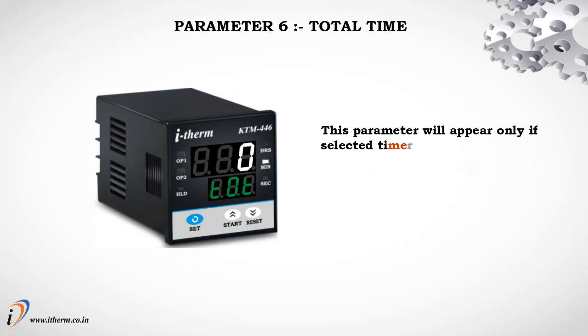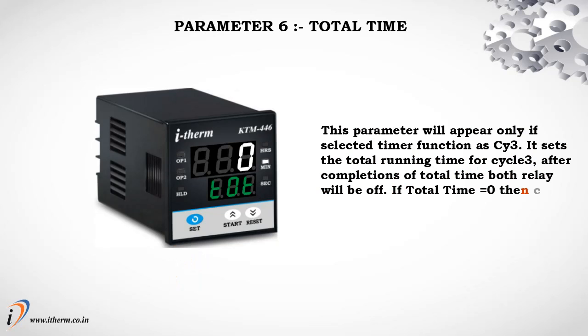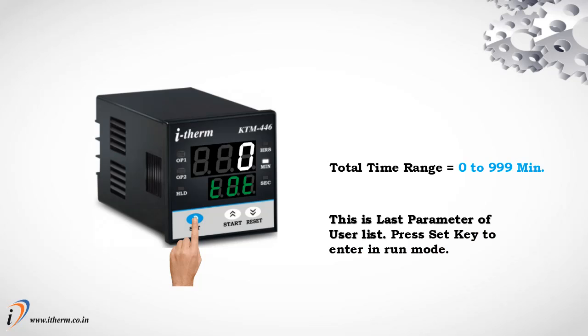Parameter 6, total time. This parameter will appear only if selected timer function is cycle 3. It sets the total running time for cycle 3. After completion of total time, both relays will be off. If total time equals 0, then cycle will run continuously until reset pulse. Total time range 0 to 999 minutes. This is the last parameter of user list. Press set key to enter in run mode.